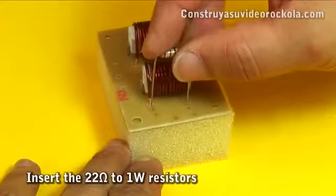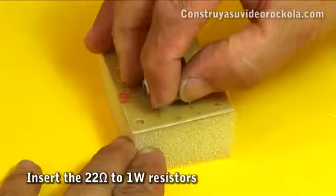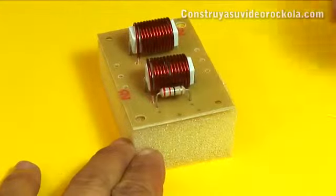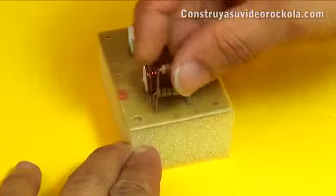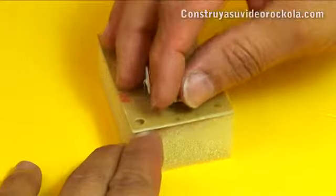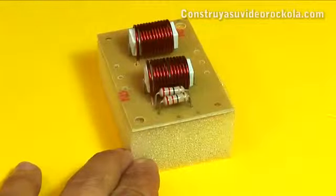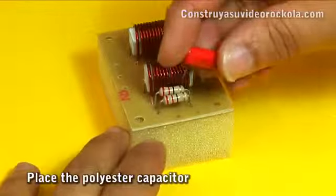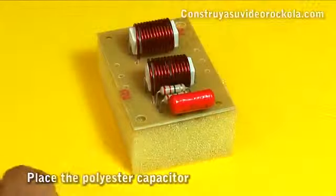Now place the 22 ohm resistors in their respective place. Remember that as the resistors are connected in parallel, they become a single resistor, of 11 ohms, 2 watts. And we put the 0.1 microfarad capacitor in its respective place.